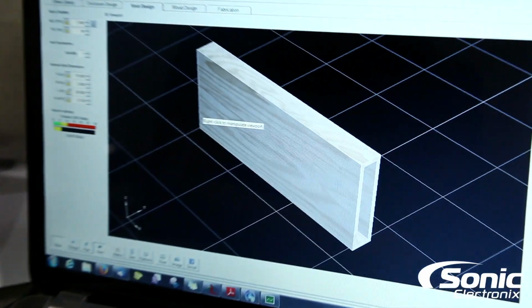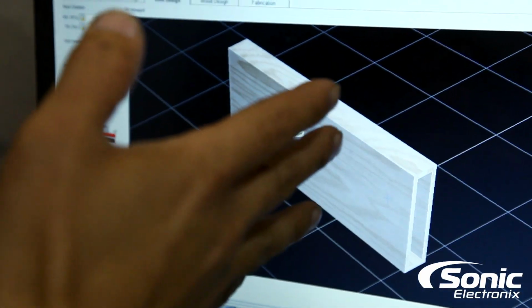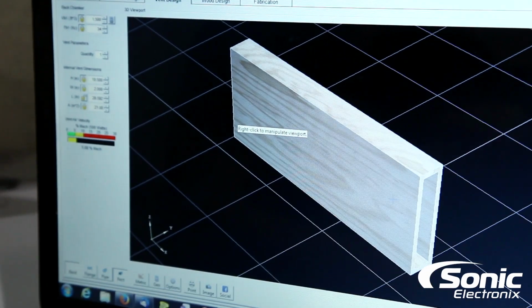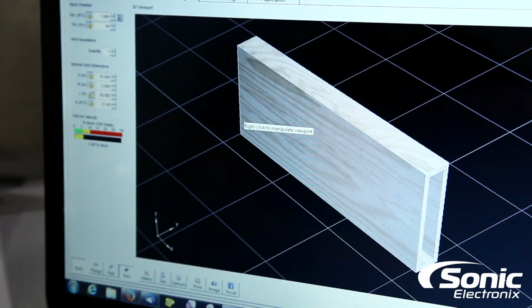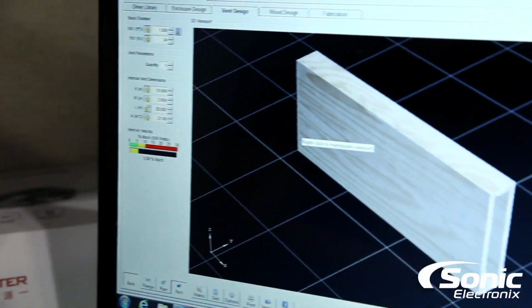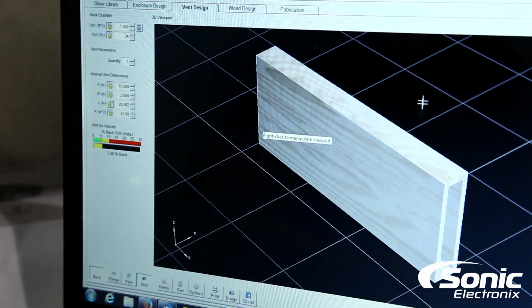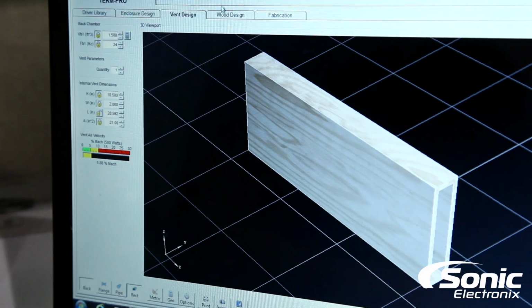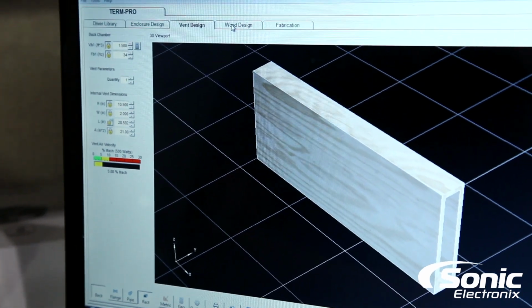Here's the port. Now, of course, it doesn't matter if it's just a straight port that's 28 inches long, 28.5, or if it's an L shape, or whatever shape it has to be to get that length. I just know that 28.5 is probably gonna work for me for the width of the box that I have for this trunk. So if you remember last time, we were at a little over 8 cubic feet before. Now we're gonna go to our next tab because this is what is acceptable to us.